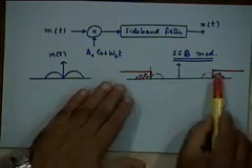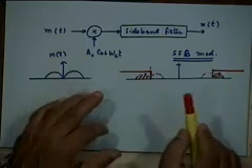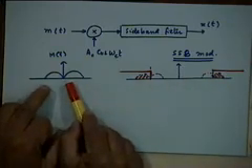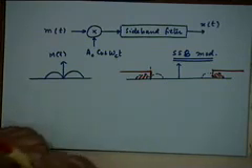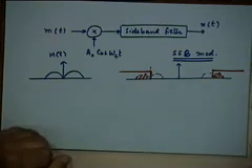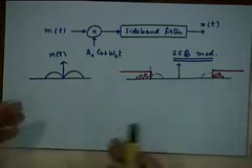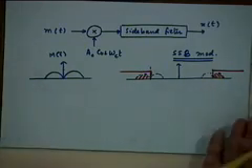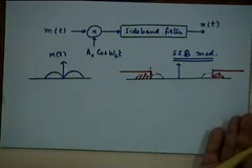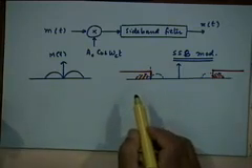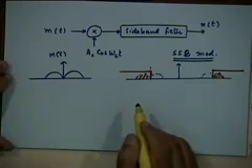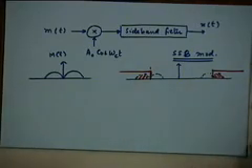Suppose we retain the upper sideband. Now how do I get this message signal back? How do I do the demodulation? Can anyone suggest? Because if I can't demodulate, then this whole exercise is wasteful. It doesn't help anything, right? What should I do as a demodulator? Any answers? The demodulator remains the same synchronous demodulator that we had for DSB-SC. Absolutely no difference.